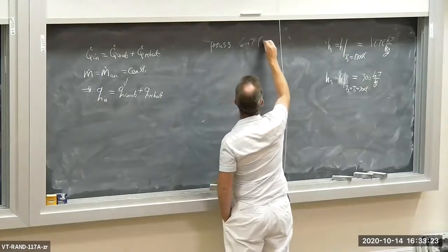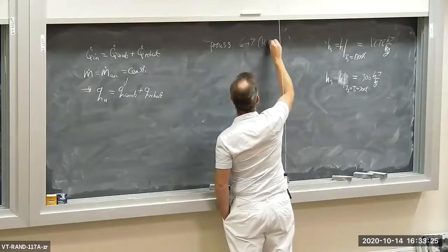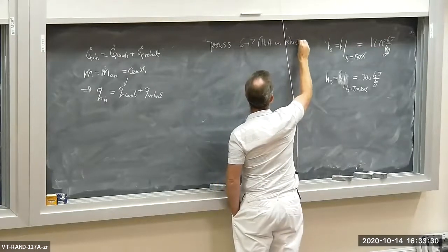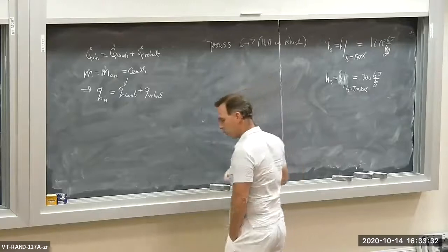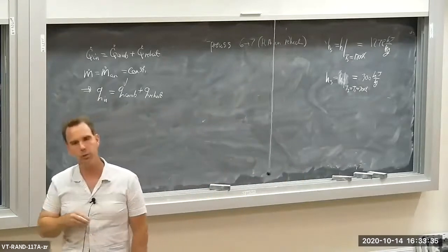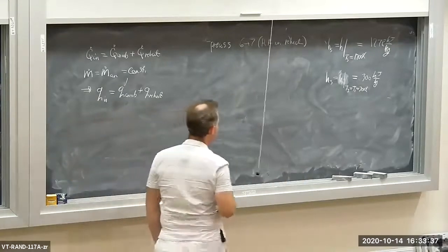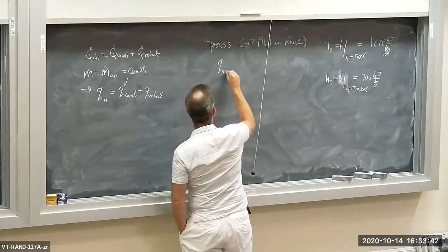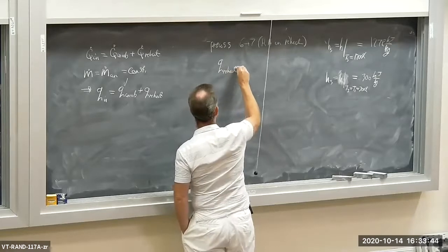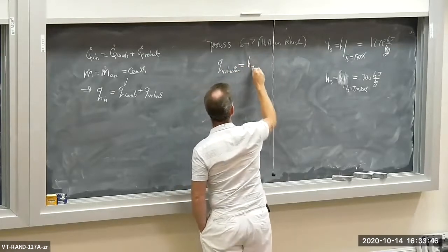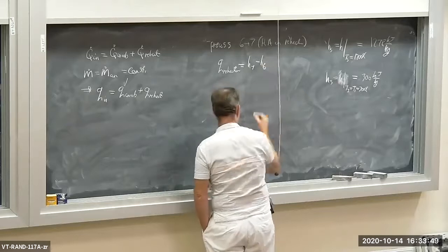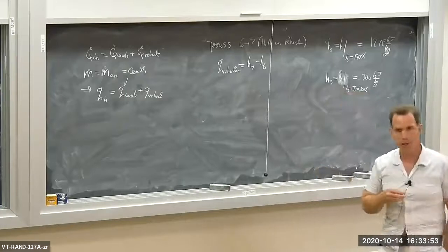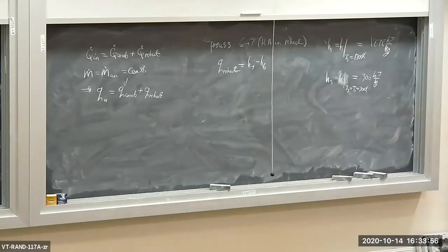So this is heat addition in reheater. I apply an energy balance to the reheater. Steady state. No change in kinetic and potential energy. No work. And I get H7 minus H6, the specific heat added, kilojoules per kilogram of flow to the reheater.